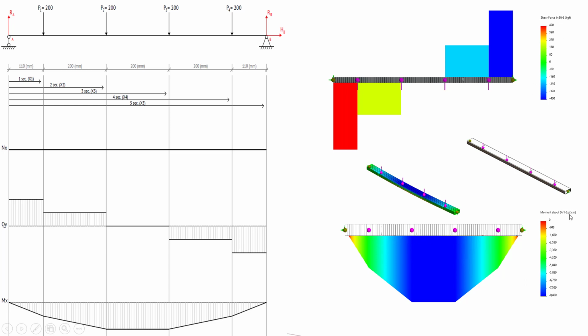Coming to the bending moment, if I convert it to kg per centimeter, it is the same here. We have got 84,000, so if I convert it to the same unit system, we'll have the same 84,000 only. According to that, this is the same bending chart. This is how you can compare the practical scenario of a simply supported beam with the hand calculations as well as by using the internet. That is also the best way to deal with this kind of steps. And if you want to validate with software, that also we have seen.